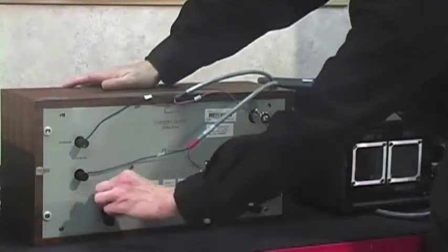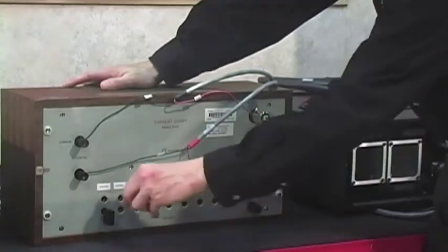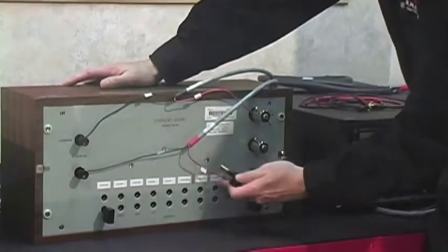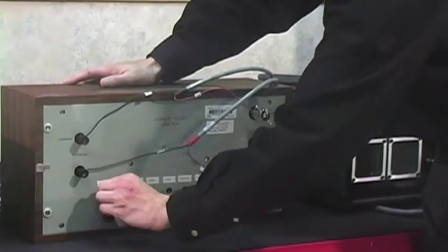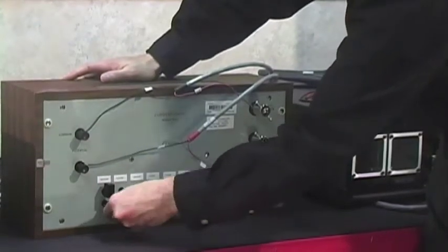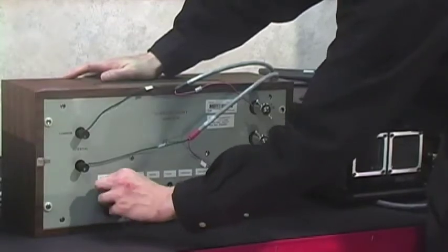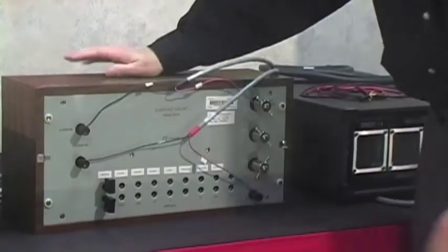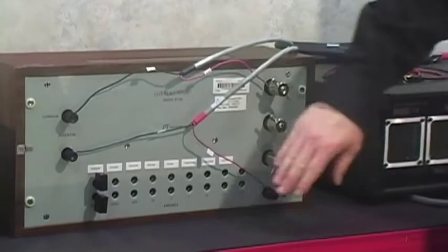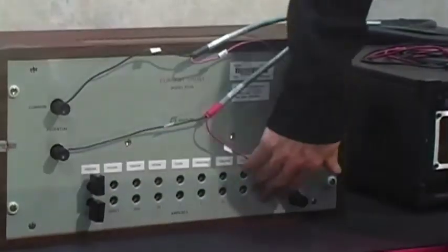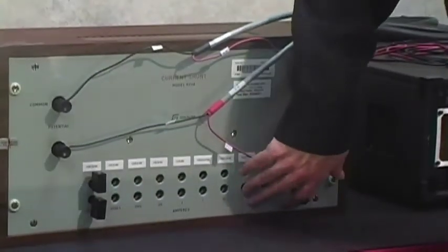You'll make sure that these pegs, which can come out and basically go in anywhere along the different ranges that are specified, are placed in and securely placed in, and usually we'll put them in and you'll just twist them to make sure they got a good secure connection. And so that'll be the initial setup, because you always start with the high value first to work your way down to the low resistance, high current value.